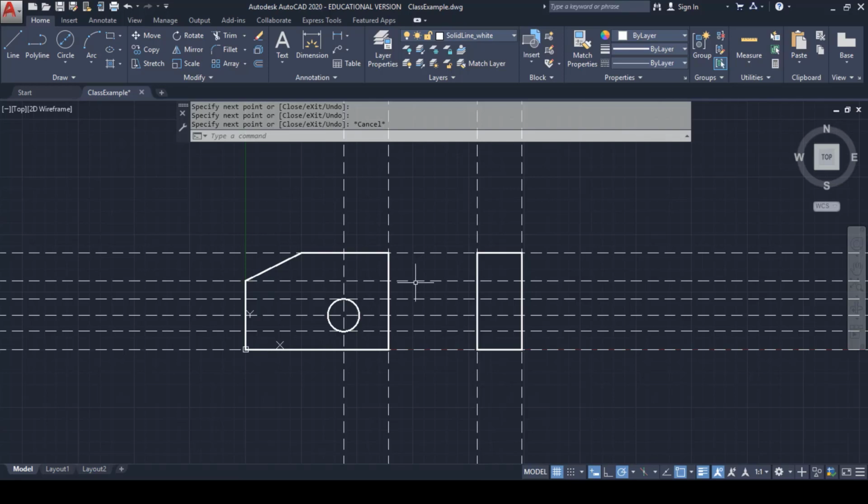And if I'm looking from the right to the left of the part with the side view, then this line I cannot see it because it's hidden. Also, all the intersection lines here, I cannot see them, but they do exist. So I will need to put hidden lines here. So I'm going to select the hidden line and put a hidden line from here to here, and also a hidden line from here to here. Then once again from here to here. So those are the hidden lines.